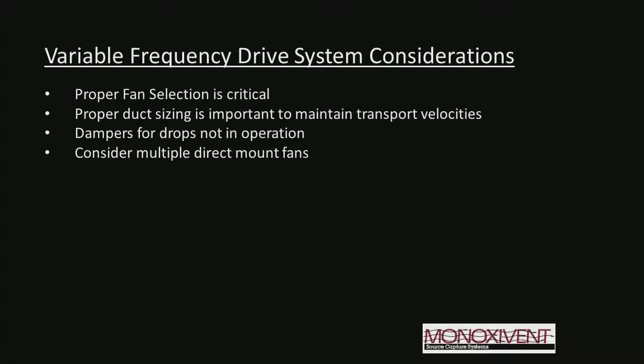You will need dampers or some way to shut off the drops that are not going to be used. We're going to have 10 drops in a system, and we want to be able to shut some of those off so that we could slow the fan down and save some energy. We really want to make sure we put dampers in, as well as make sure that the people that are using the system use those dampers religiously. A lot of times what will happen is you have dampers in all those drops. They're either going to be all open or all closed, and nobody's paying attention to what's going on.